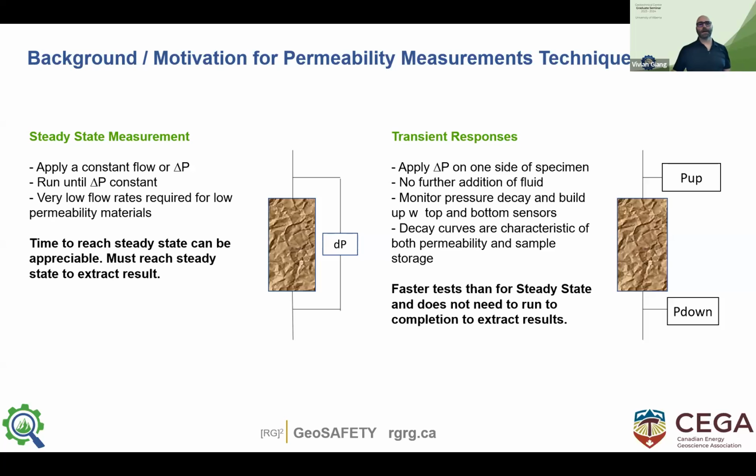So generally two types of techniques to measure permeability. One is through steady state measurement, very commonly done. Darcy's law, we do it all the time in geotech. Or a transient permeability approach, which is a technique that you need to apply if your permeability is getting down quite low, where you can't measure volumes in an appropriate time scale. So steady state, obviously, we should all know this one.